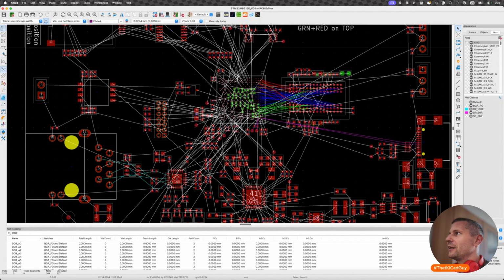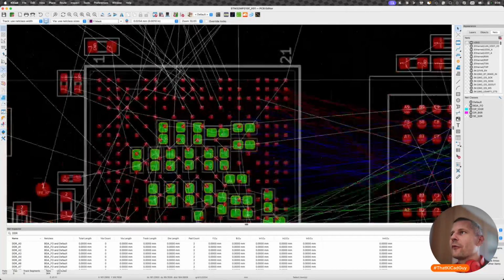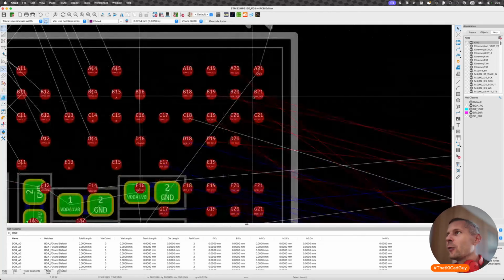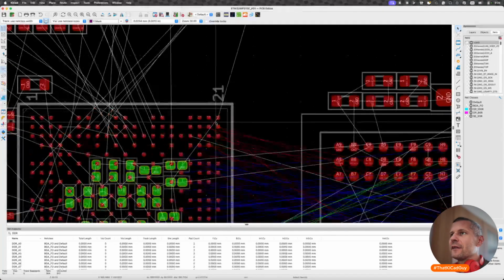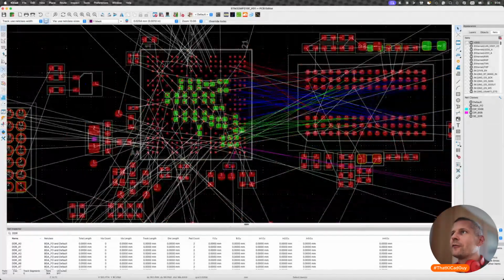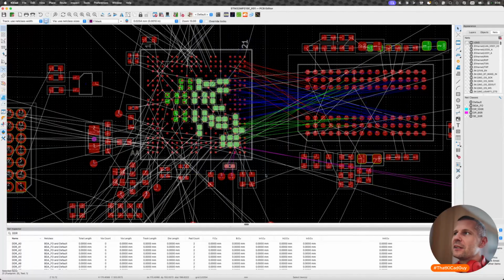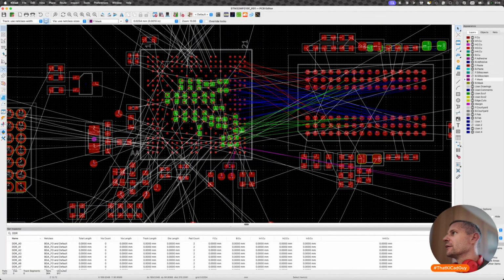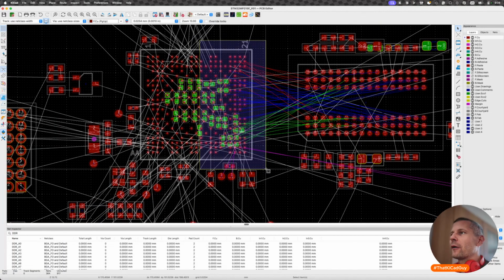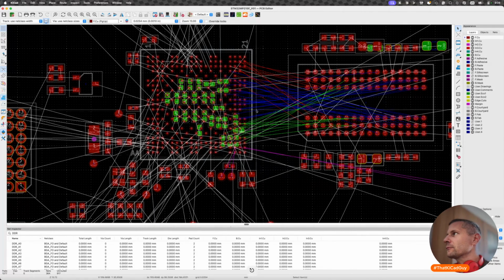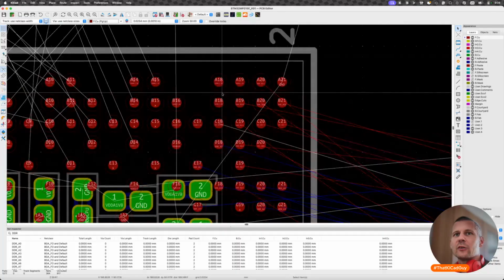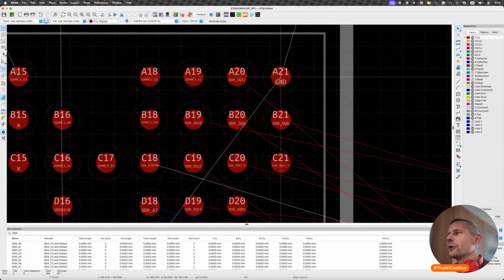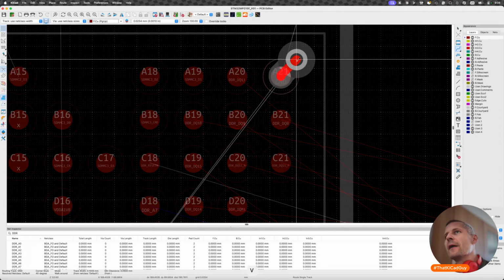But as I can see, I started with Ethernet, which is at the opposite side of the PCB, so I was not very successful with my plan. Anyway, let's start with these two quadrants of the BGA package, because these two quadrants affect our routing the most. So let's start with fanning out. I don't know what I will comment during this, but let's see.